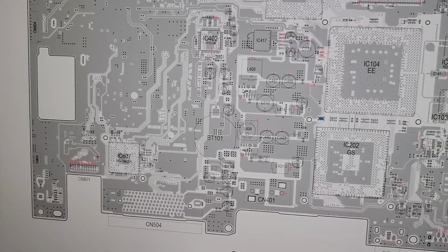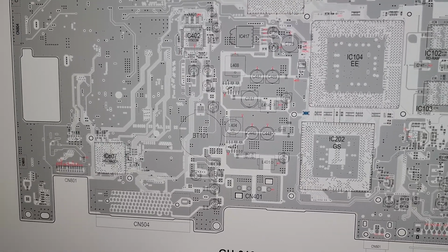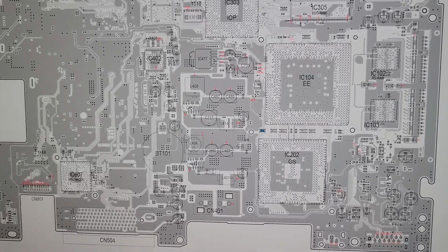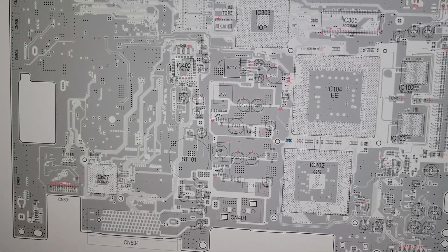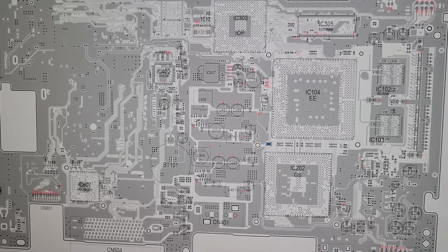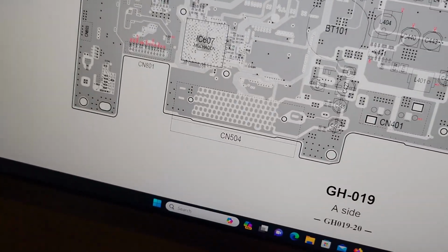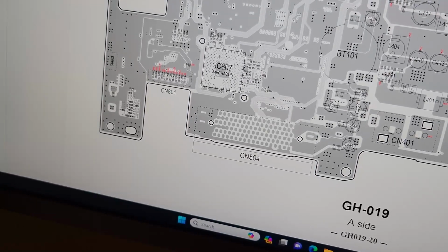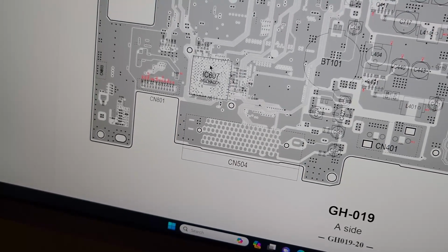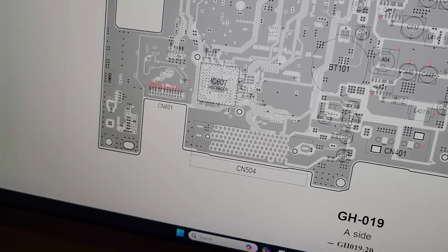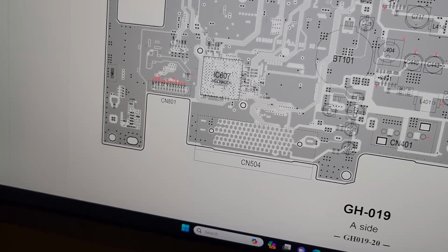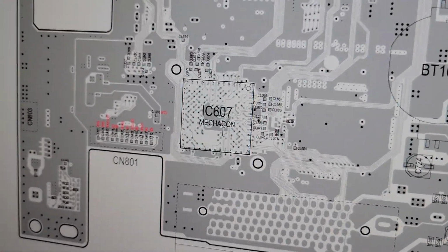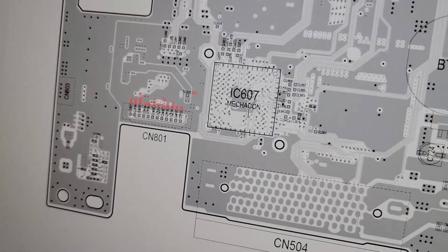So like I said, these are educational videos. You can find this stuff online if you really want to start poking around your PlayStation. That's why I keep telling you guys, if you can, give this thing a little heat. See if it starts acting right. If it starts acting right, the chip is junk. It's a BGA controller package. You can see it right there, all the little balls in it. Look at all those little vias you got to go through.